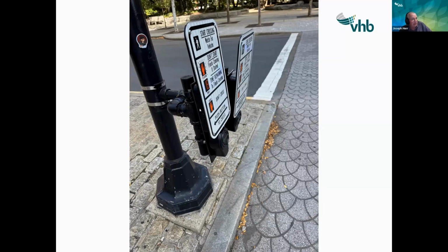And also it's on an extender arm. We'll talk a bit about the extender arm, but the button's offset from the pole so that a wheelchair has access to that button. It's usually a 10-inch reach from the wheelchair, from where the wheel can stop, to the button itself. And that's this particular type of extender arm that was put on for this application.